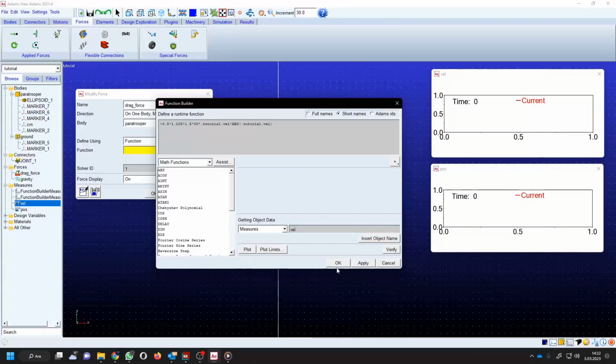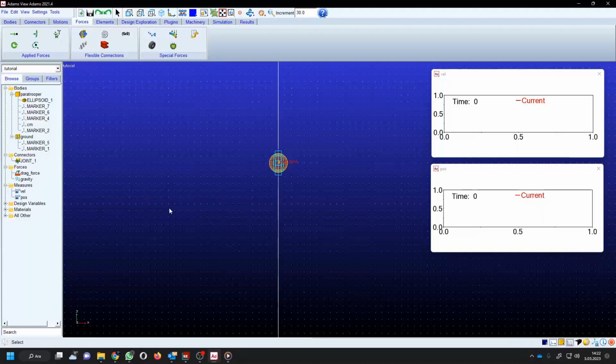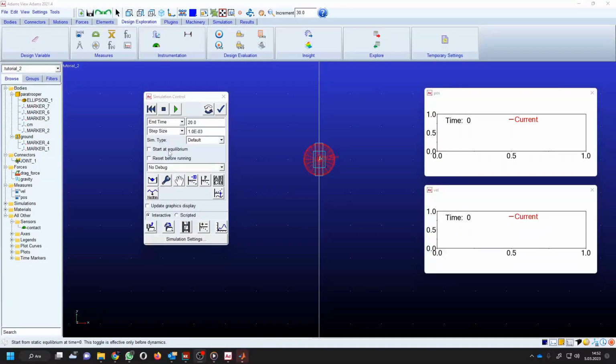Okay. So this is also okay. I had used 0.001 seconds of time step in my own solver, so I will use the same value, but we should bear in mind that this is the output time step of Adams View. As far as I know, Adams uses an implicit solver or integrator, and this uses variable time step values. So we should remember this.